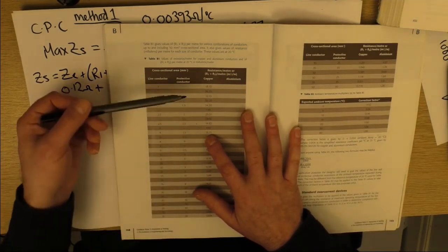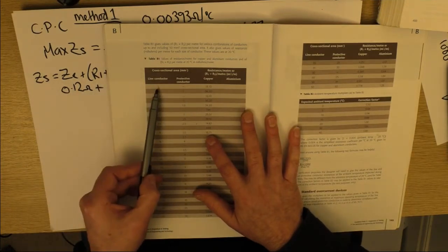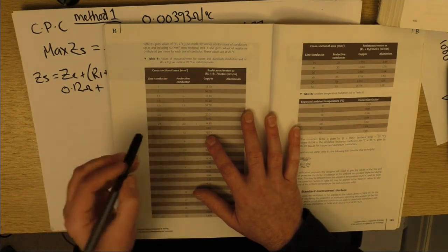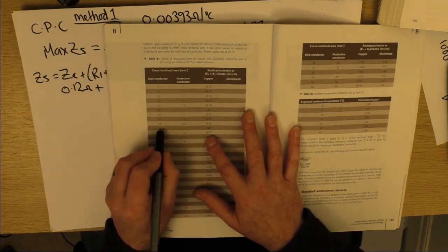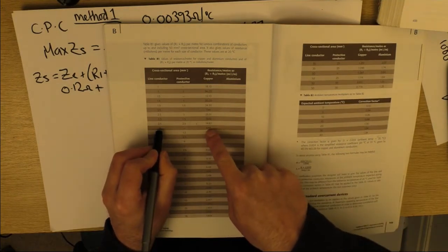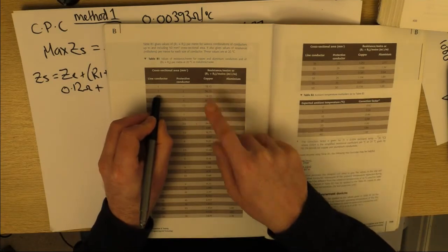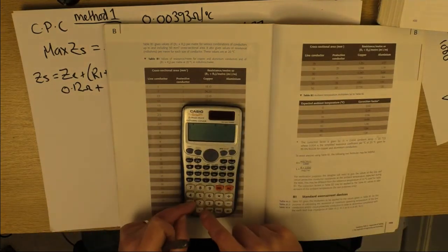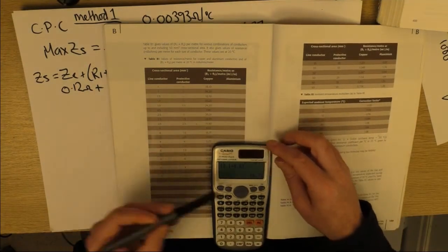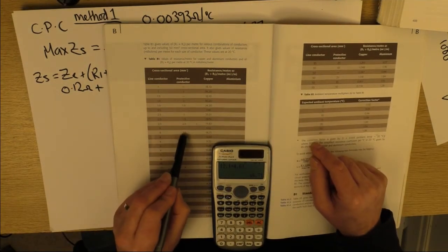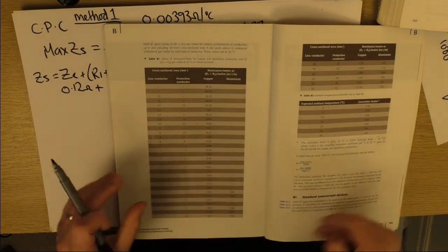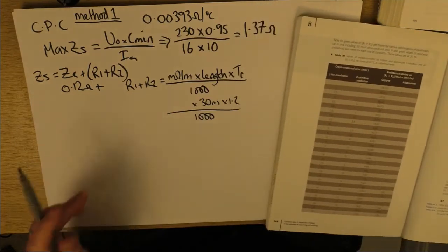This is a handy table. It gives you individual conductors, but it also gives you these handy combinations. So what I could do is take the 4 mil on its own value of 4.61 and add it to the 1.5 value of 12.10. So 12.10 plus 4.61. What do I get? I get 16.71, which is the same, isn't it? So they've done it for you. Again, cheers guys. Just makes my life so much easier.